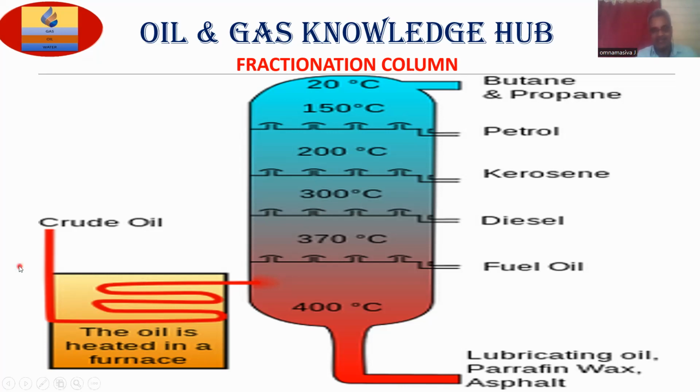Then it will enter inside the air preheater, where there will be a coil. These are chrome coils, a special material. Through the chrome coils, the liquid will be heated up to 400 to 450 degrees Celsius, and it will enter the fractionation column at say 400 degrees Celsius.